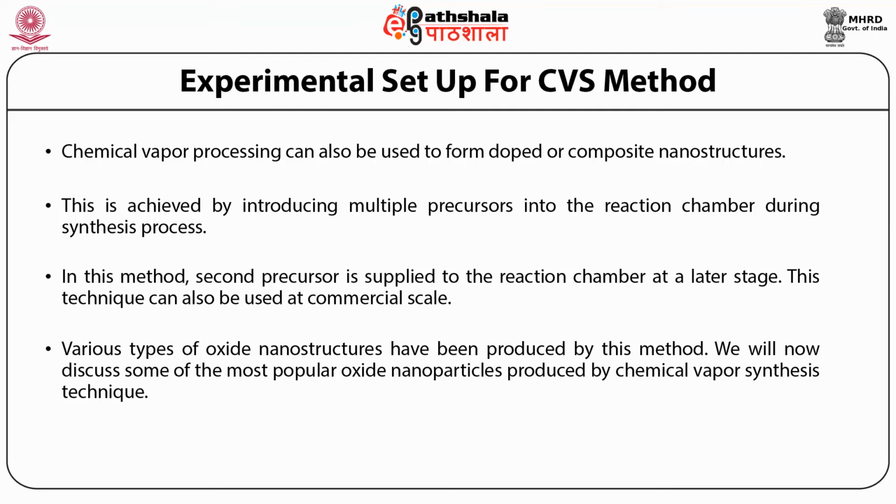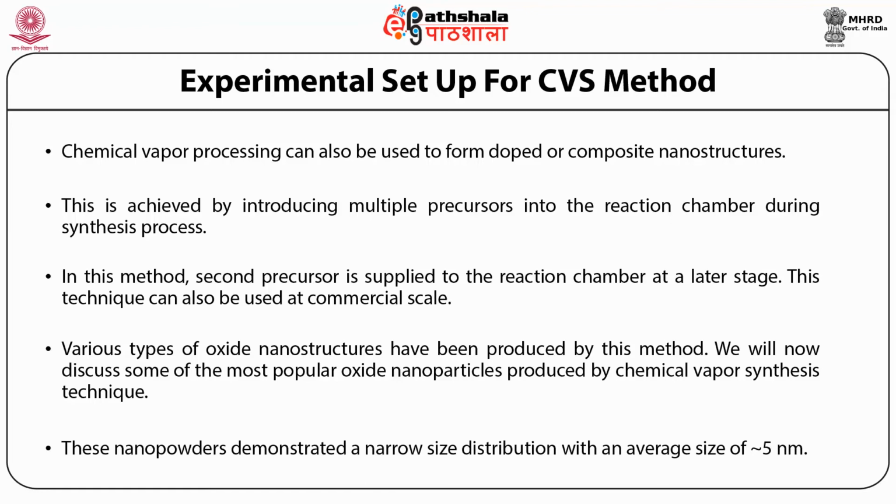We will now discuss some of the most popular oxide nanoparticles which are produced by the chemical vapor synthesis technique. Nano-sized particles of the oxides of indium, tin, and tin oxide doped indium oxide are synthesized by chemical vapor synthesis for their application in transparent conducting oxides, catalysts, as well as sensing devices. These nanopowders demonstrated a narrow size distribution with an average size of approximately 5 nanometer.